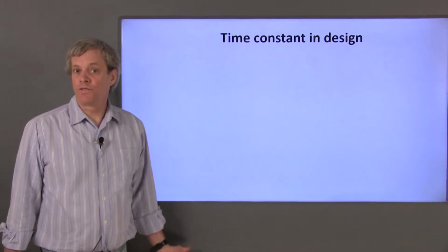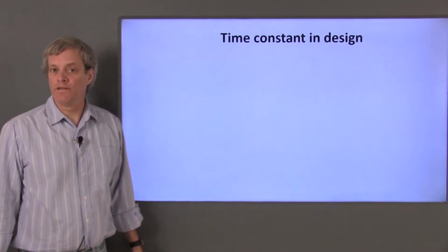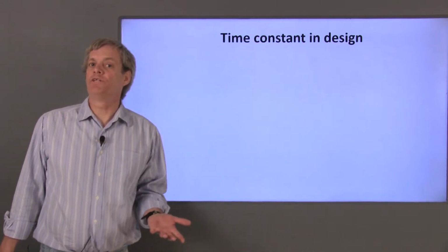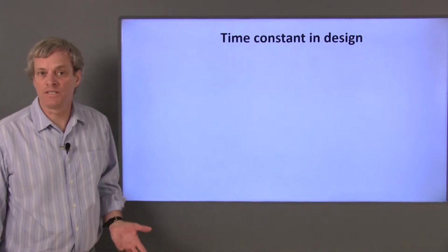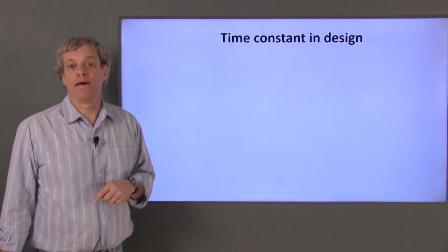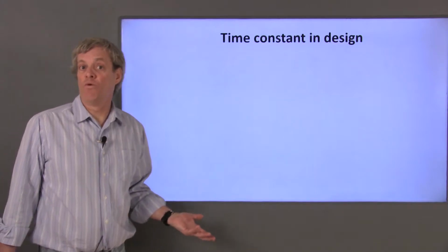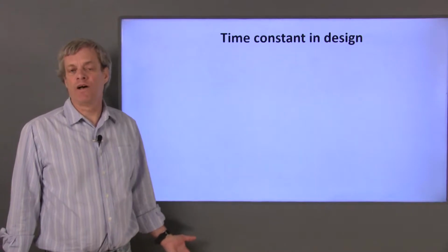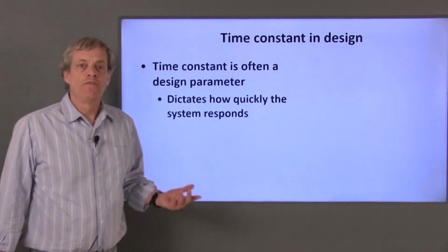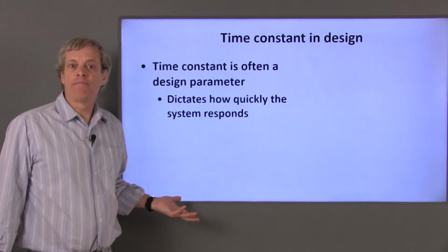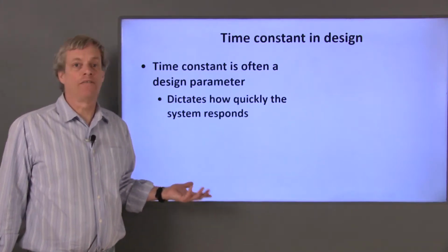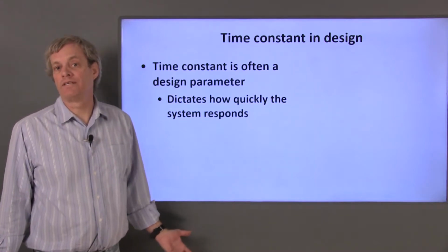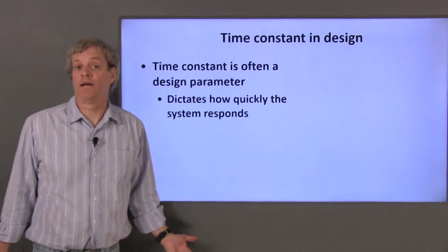The approach here is also very similar to the design process we used for linear systems. In linear systems, we had an equation describing the system operation in terms of the component values for the system. Then, given a mathematical relationship in terms of the slope and the y-intercept that the system should implement, we could choose component values that provided the desired relationship. The only difference here is that the mathematical process to be implemented will be based on the time constant, since in energy storage we're interested in how quickly the system responds, which is characterized by the time constant.